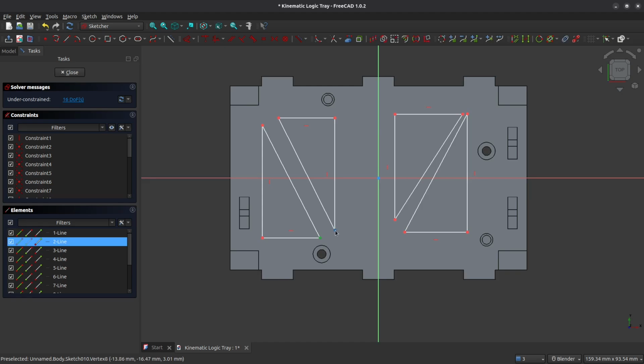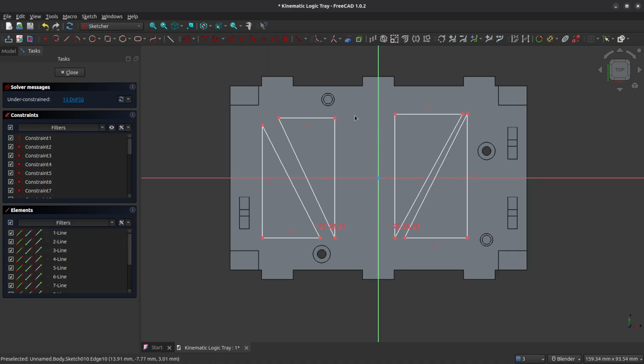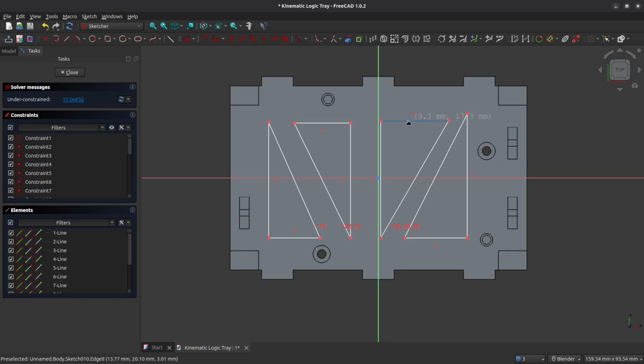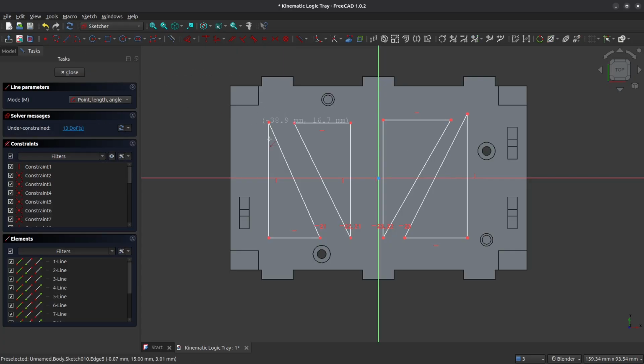Now we're going to make the points of the bottom of our triangles so that they are collinear. I constrain them horizontally. And now we're going to modify the spacing between these triangles. So we're going to toggle on our construction geometry and grab the Create Line tool. And we will create lines between the top points of these triangles.